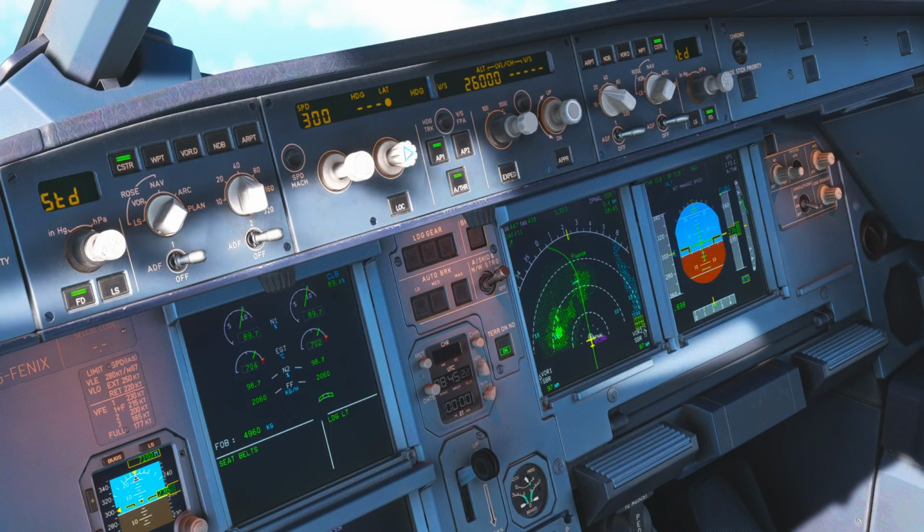To take manual control, the pilot can pull the knobs for airspeed, heading, altitude, and vertical speed. The current airspeed, heading, and vertical speed are then put into the digital display, and the pilot can rotate the knobs to change the selected values, and the autopilot will immediately fly towards the new target value in the selected mode.